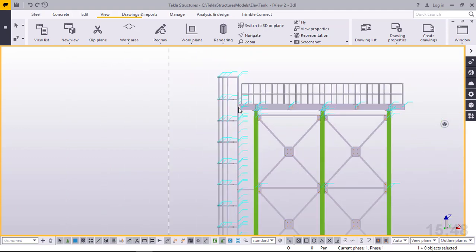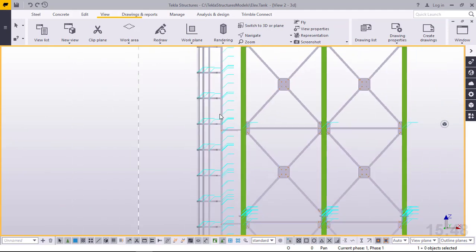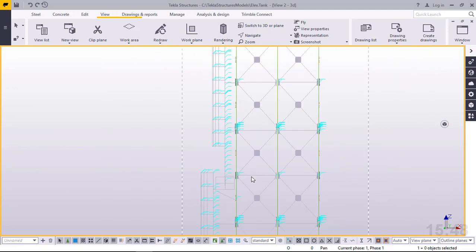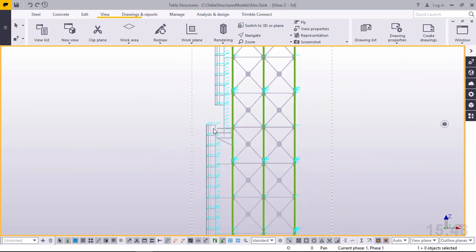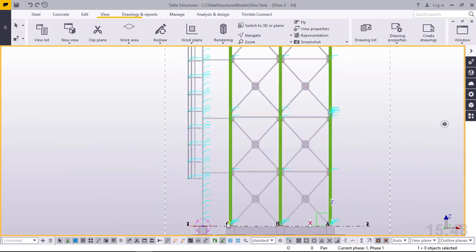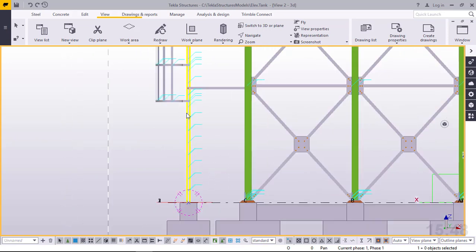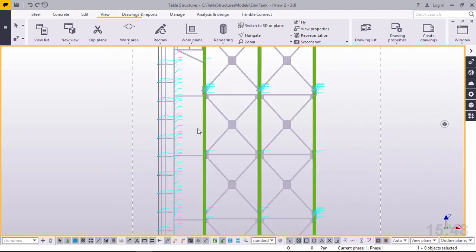You can see the support for our cage ladder right there, and another one supported here, and there's another support here at the bottom end, and there's another flight that starts from the 0 level here, going all the way from here to here is 2 meters high. From ground level to the start of the cage is 2 meters. Now this is how it looks, and this is how the support looks.